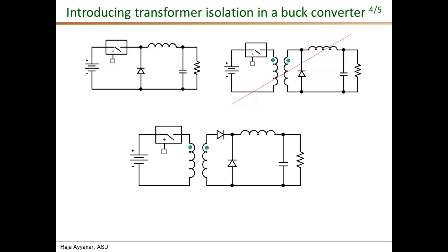All I've done differently is I've added this diode here, and that makes this winding not directly in parallel across this diode. Okay. So is this a valid circuit? It is still not a valid circuit because by introducing this diode here, I have violated the flux continuity principle.